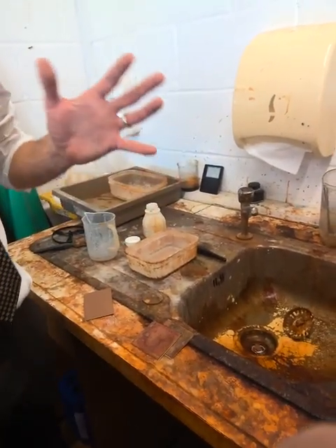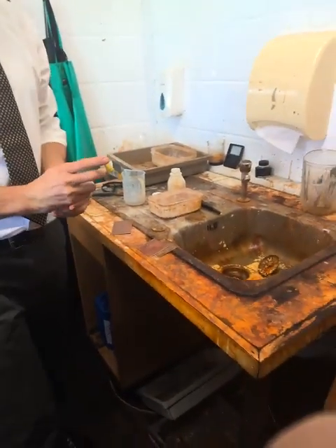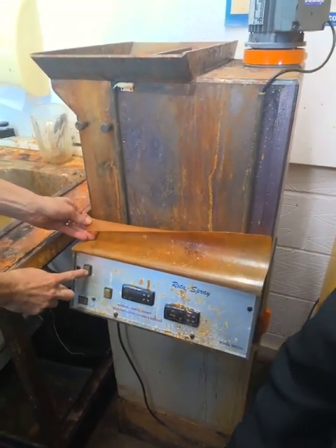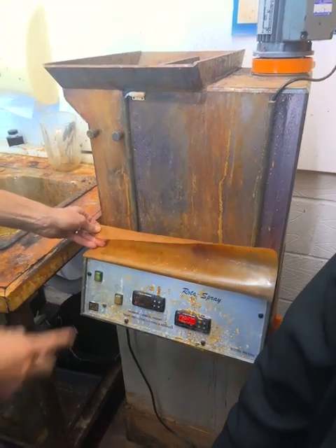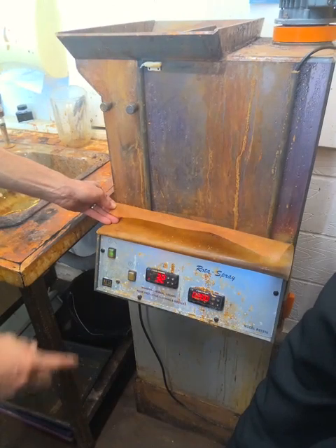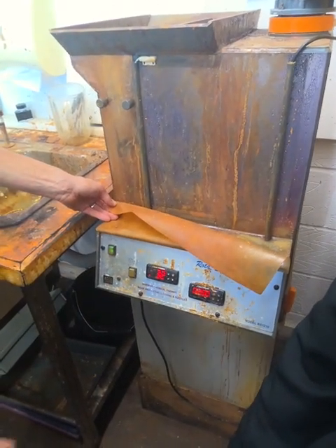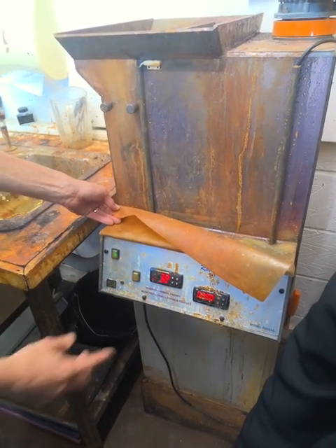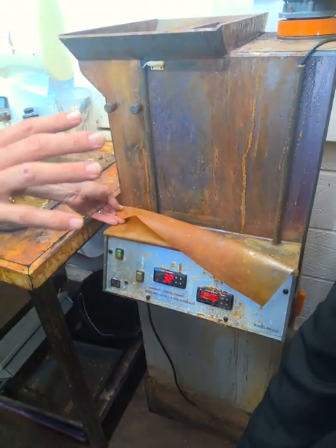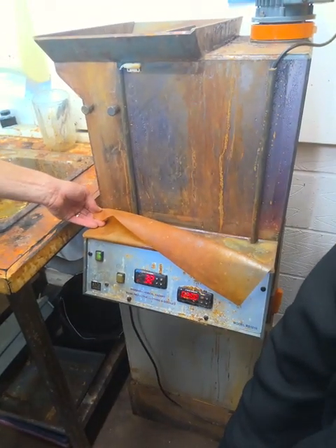So once we've done that, can you all move back about 2 paces, please? We need to go to the etching machine. Now the etching machine is here. The etching machine needs to heat up to 42 degrees. If I was to turn this on now, it's probably going to be about 20 degrees or so. Let's wait, it's on 32. Someone's obviously had this on. That'll be about room temperature, about 20 degrees, depending upon what time of year. And what we need to do is wait for that to heat up to 42 degrees. Around 42 degrees is when it's most effective, where the acid etches in the most efficient way.